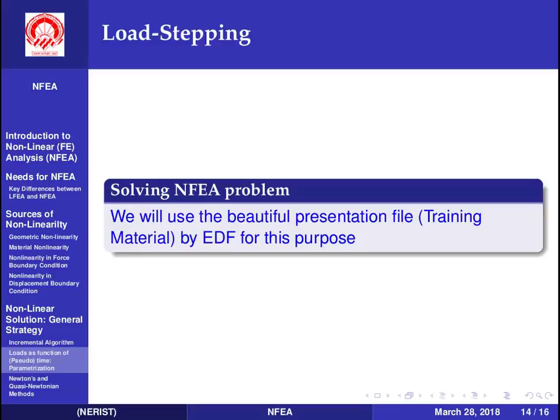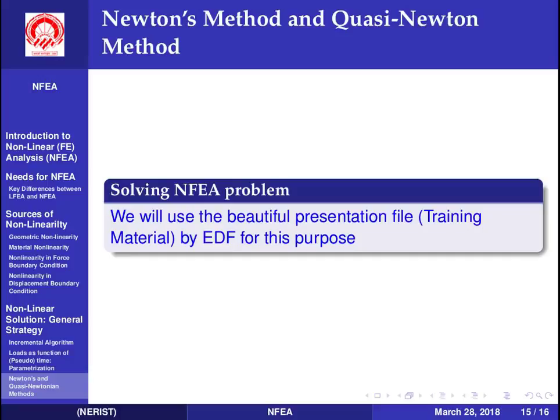In a nonlinear problem, we cannot apply the load in a single go, because that will be too nonlinear to solve practically, and therefore what we do to cut the nonlinearity, we apply the load in terms of various load steps. That will reduce the level of nonlinearity in the problem, and that will ease the process of solution. So those load stepping topics I will discuss, and again I will use their file for that purpose.